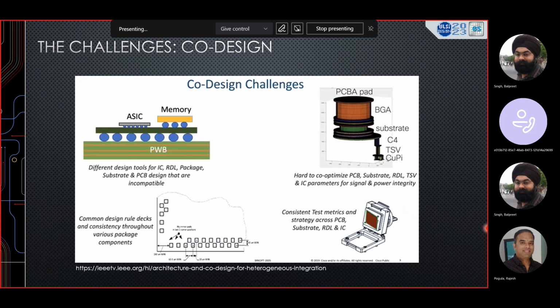And we were talking about the rule decks as well. When we assemble all these different pieces, how are the micro bumps aligning together, or how are the copper to copper bumps aligning together physically? How can we predict or analyze that alignment upfront in our design cycles, so that when I deliver a chip to you, I can put them together physically in the assembly process? So that is about standardizing the design rule deck. We can have a standard suite of rules we pass to the tool, so that when we bring in the chips, we can verify them upfront before we put them together.